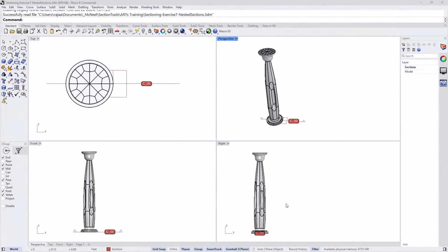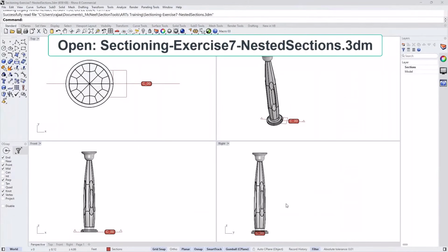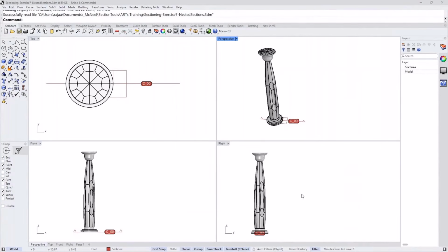Okay, that is the last part, which shouldn't take a long time, to show you some other functionalities available now with sectioning, with extracting sections. We did one part in the beginning, which is extract a slice, and we use that slice to subtract from the model, like Brandy asked in the beginning of the presentation, and that is one use case for it. But there is another use case when you extract the sections and want to lay them out on the XY plane and prep them to export for laser cutting, for example.